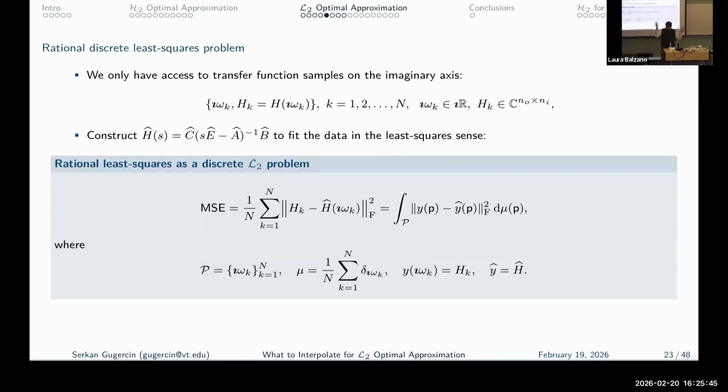You write this matrix, and going back to Anderson and Antoulas in the 1980s, what they showed is that if this data came from an underlying linear dynamical system, the rank of this Loewner matrix tells you the order, so you can guess these things. We have other techniques too, but this is given R. With some other techniques you do a greedy search, increasing the order one by one, and then you stop, but it doesn't give you the L2 optimality I'm talking about. Is that answering your question?